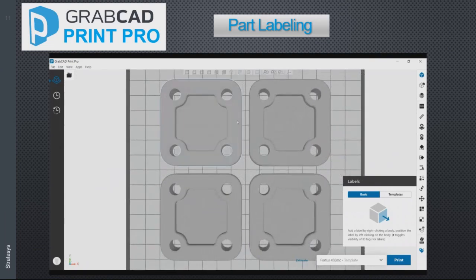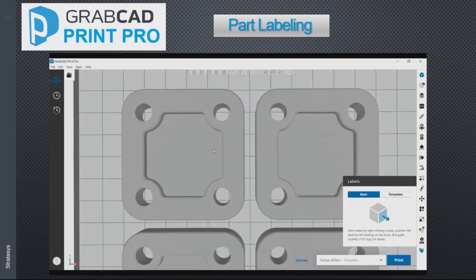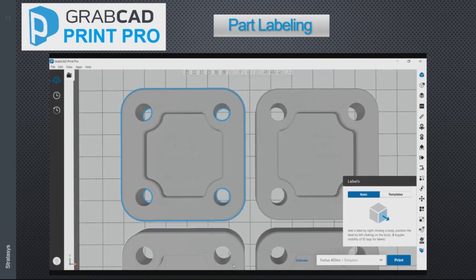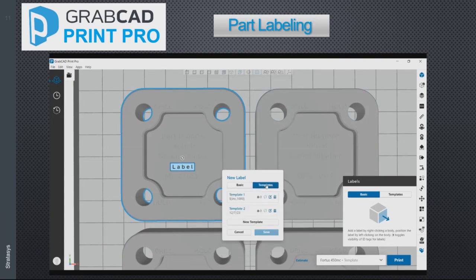So I'm going to go to the top view here. I'm just going to label these top 2 up at the top. Right click on the part that I want to label, and I'll go down to add label to body. And then it will allow me to select the location where I want to put the label. And then I can type in whatever I want into here. But to save some time, I've built a couple templates so I can quickly label a whole bunch of parts.